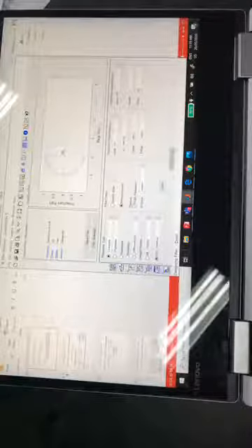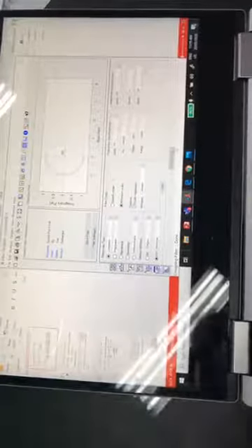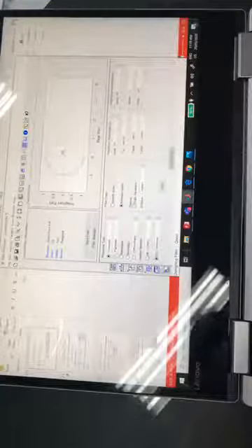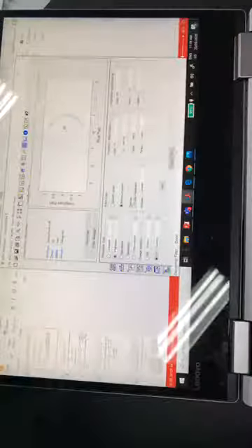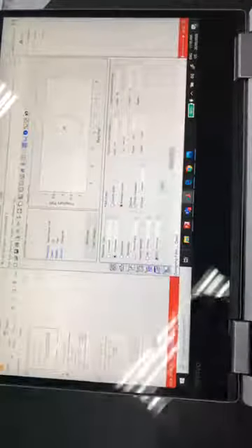So if you design a high pass, you see the location of zeros has changed. Now the clusters of 4 are on the high pass spectrum, and the zeros are placed on the unit circle, and they will not let this frequency pass.